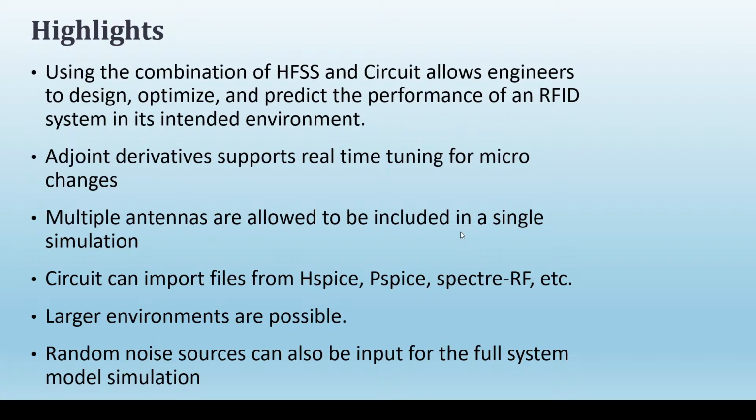Another thing is you can also inject a random noise source into your full system model. Right now the RF source we are using is ideal, but you are always welcome to inject random noises into your system that you think might affect your radiation pattern or the performance of your design.